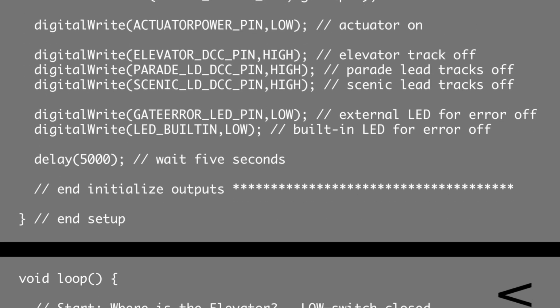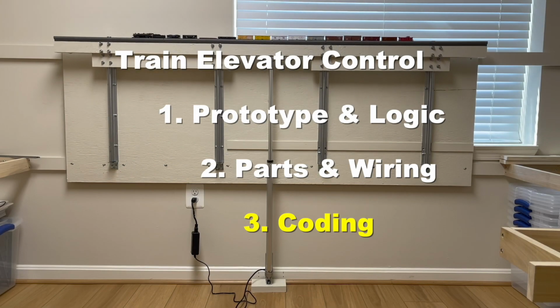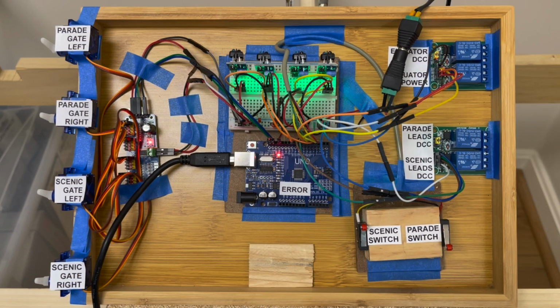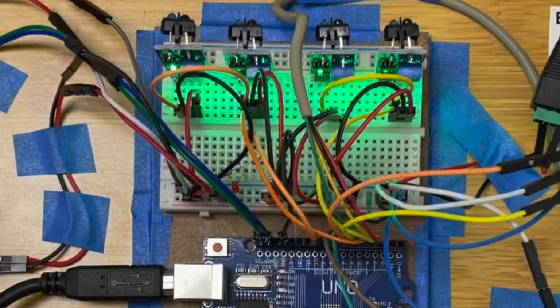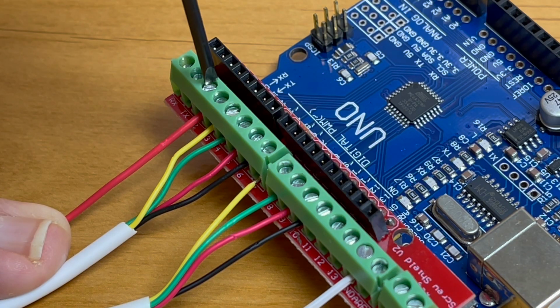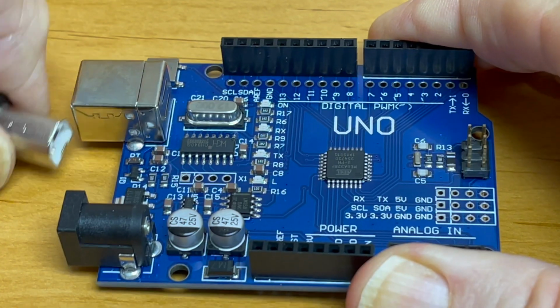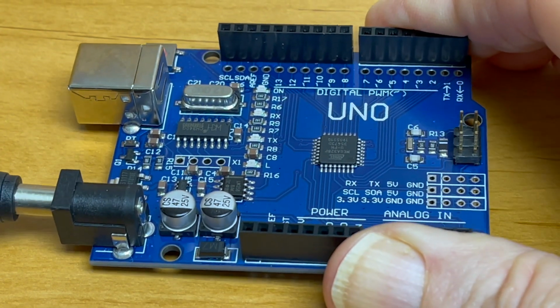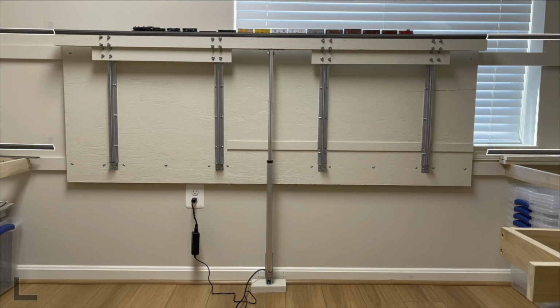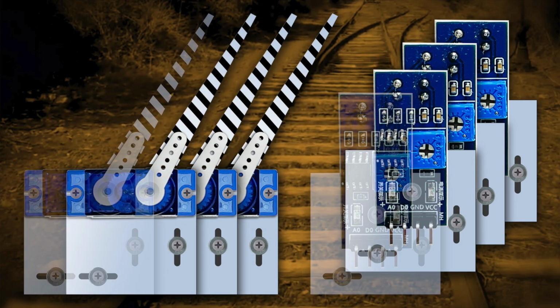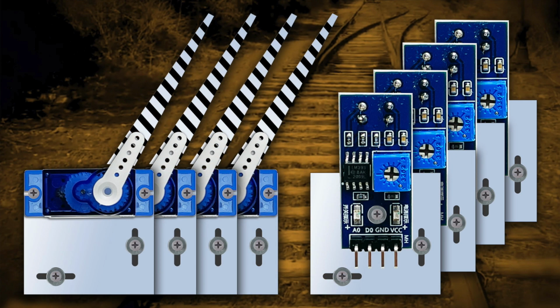Before wrapping up this video series, I want to briefly discuss what will be required to convert my control system prototype for permanent installation on my train layout. Instead of the breadboard and jumper wires, I'll install terminal blocks and permanent wires. I'll disconnect the USB and power the Uno with a 9-volt DC power supply. And I'll need to mount the infrared sensors and servo motors next to the lead train tracks. I'll make the mounts for the sensors and servos adjustable for exact positioning.